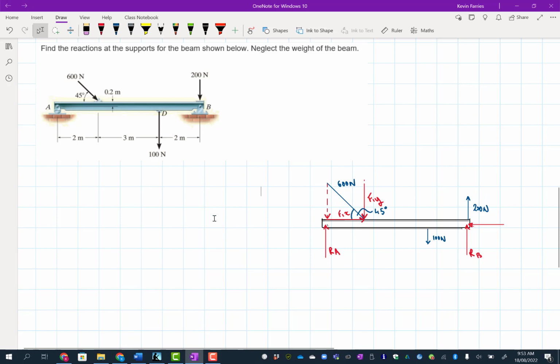Right, so we're about ready to get started now. What I would probably do first, let me just have a think about what I'd do first. Let's start with the forces, and we'll figure out what the reactions are. I haven't labelled these. So we've got RBX here, and RBY going upwards. B because it's at point B, X because it's in the X direction. Cool. We already said we've only got one X component of the applied forces, so let's start with that.